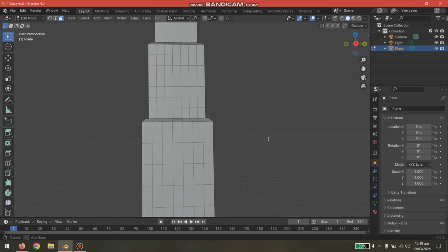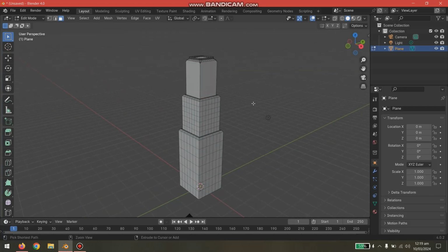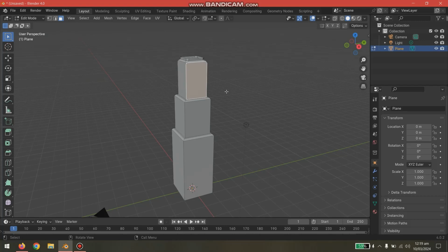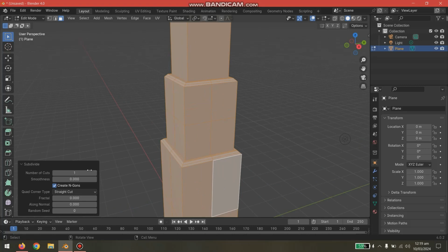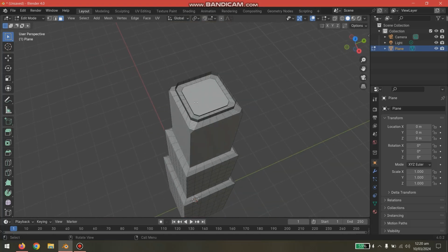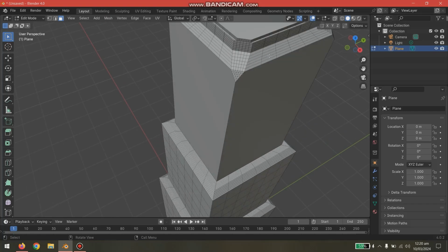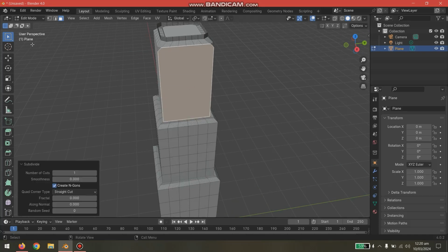Okay, so this is how the building will look now. I don't know why it did not subdivide in this area. To clear it, simply select all, subdivide, do it again, and then you will realize that it's not doing it again. But there's nothing too complicated science here. This is happening because you did the bevel. So this shape has this bevel and its own subdivisions, so now this area will not be subdivided. Okay, so there are other methods like scissor to cut out.